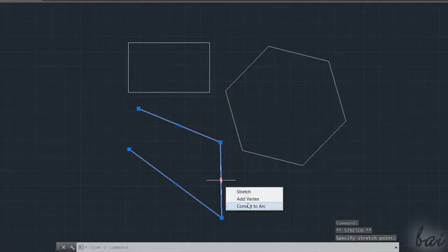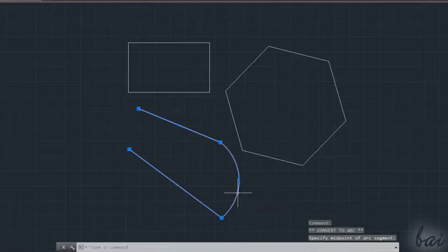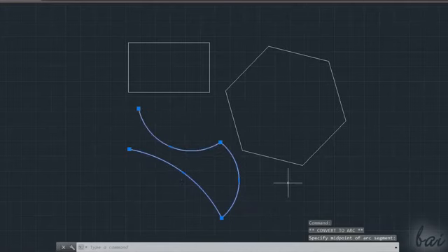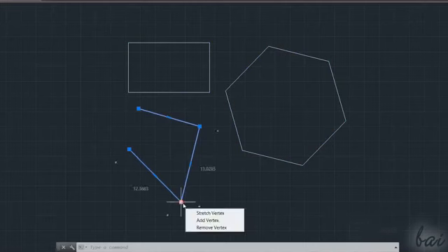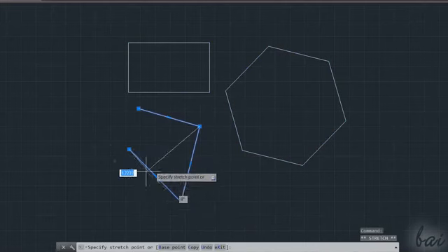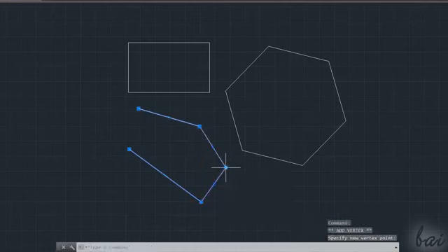Very important are the polylines, which are 2D objects used to create complete personalized shapes, either straight or curved. You draw polylines by using the polyline, the rectangle, and the polygon tools. When you select a polyline, you will get big and small blue nodes on it. Hover on the big ones to get length and angles measurement, and use Stretch Vertex to move such vertex, editing the object shape. Use Add or Remove Vertex to add or remove sides from the polyline.